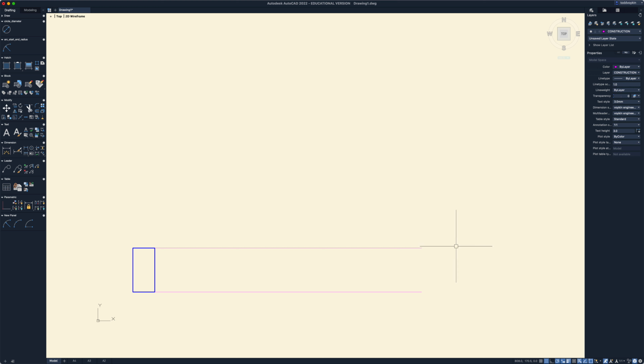Okay, now what I need to do is create a door frame on the right hand side, and again I could switch back to my object layer, and I could use the rectangle command, I could use the line command, I could use P line for polyline, or I could just copy this and move it over there by grabbing this side and placing it right there.